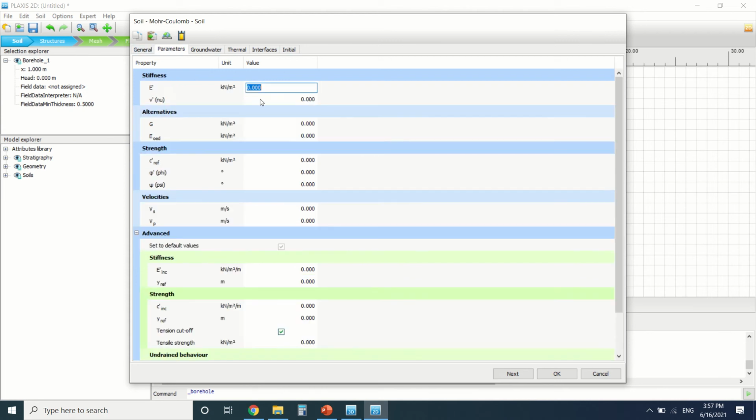Here are the parameters. I'm gonna choose a 2000 stiffness. Here I obtain all the values by default. Here is the friction angle, which I put the 10. The phi angle, which I put the 4. And I've also made separate tutorials about each and every parameter in the material.